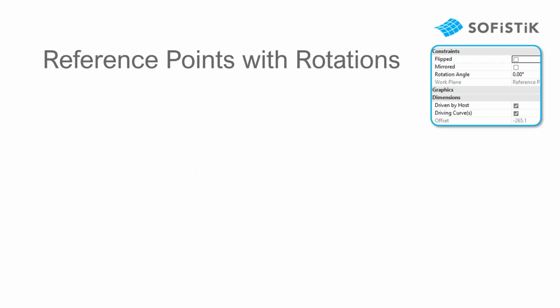Additionally, I want to take special note to the rotation angle. So here we have our adaptive point. This is the one we start with when we create an adaptive family. When we assign a point in the right plane and assign a rotation angle, this point can now rotate. So meaning that the rotation angle, depending on the plane that we select, is displayed here.